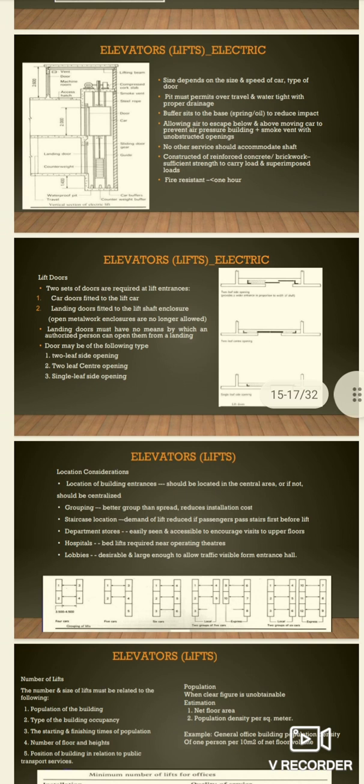Elevator lift electric. Size depends on the size and speed of car, type of doors, and pit must permit overtravel and be watertight with proper drainage. Buffer seats to the base or spring or oil to reduce impact. So next, the elevator lift electric,